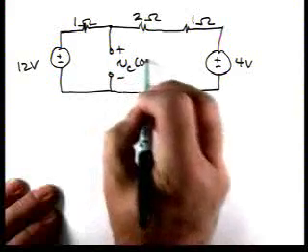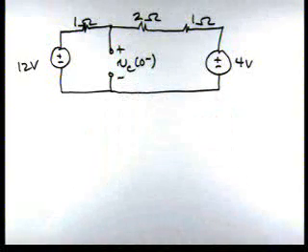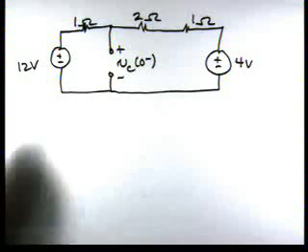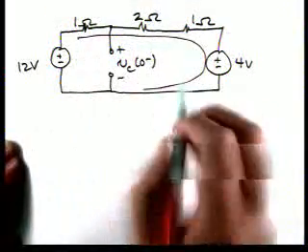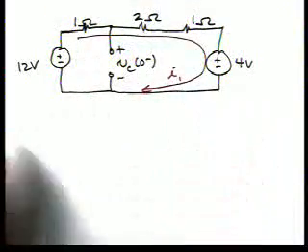Here's our capacitor voltage that we're looking to solve for. And we note now that, for instance, the voltage V0 has disappeared from the circuit because of the source transformations. Now, this is really a single loop circuit with a single current I1.